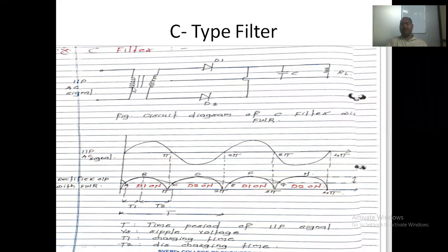In the primary there should be the higher winding, because it is connected to 230 volt, and the secondary should have fewer windings. We apply 230 volt to the primary of the transformer, and accordingly the secondary generates, say, 12 volt or 24 volt AC at the output of this transformer. Whatever the output, that is the secondary of this transformer, which type of transformer is this? Please tell me which type of transformer this is.